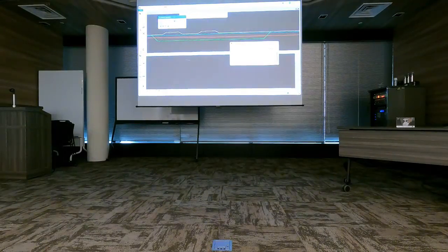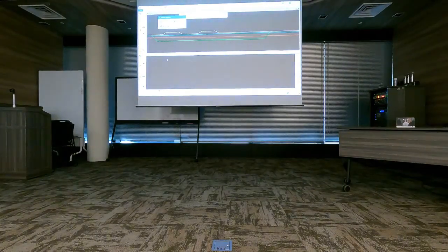I have a gravel surface which is displayed in cyan, so that is top of gravel, soil layer surface. I have 24 points, so only very little data is available for the gravel layer. I have a red bedrock surface built from 14 points. The layers other than ground have very little data. And the green surface, that's my design of an excavation, a pit design.